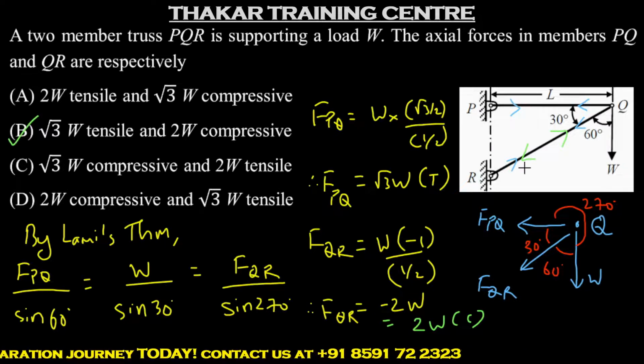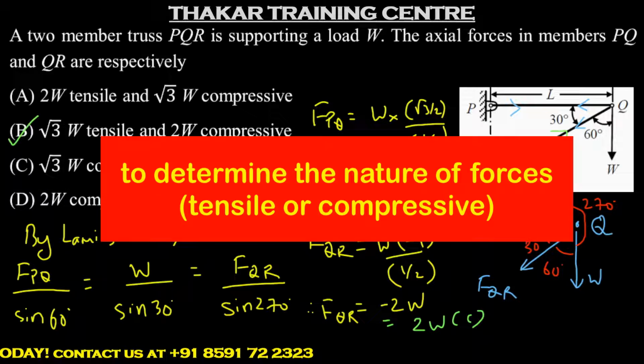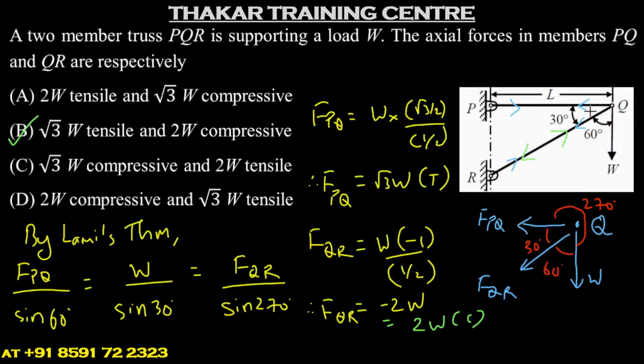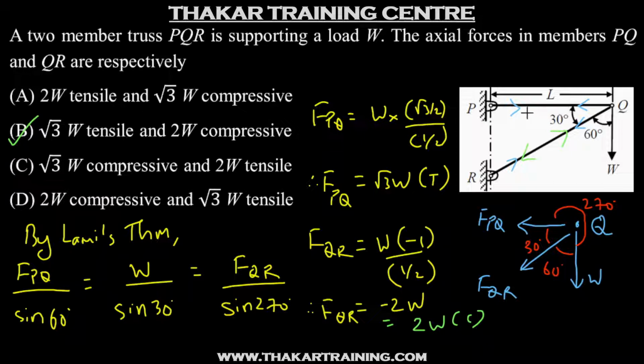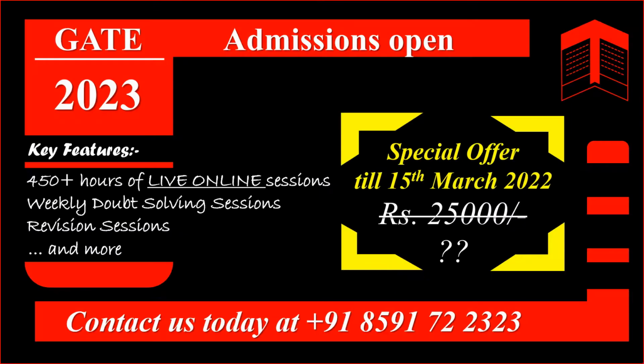You can also think of this question in an intuitive manner. You can visualize if we had some bracket like this and we had applied a force like this, this member PQ will be getting stretched. So this will be under tension, whereas this member will get compressed. I hope you can visualize this, right? So the answer will be option B.